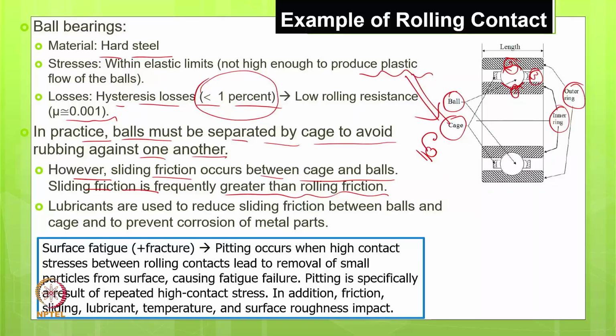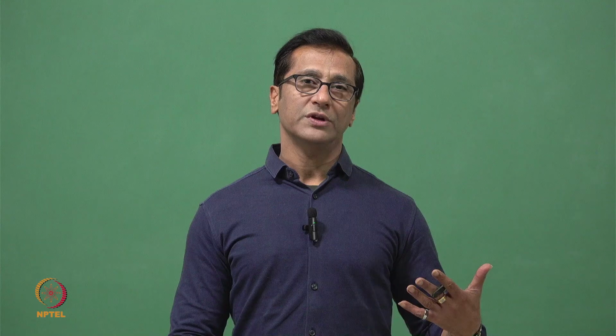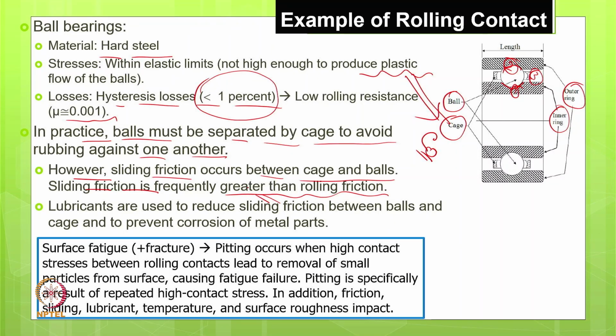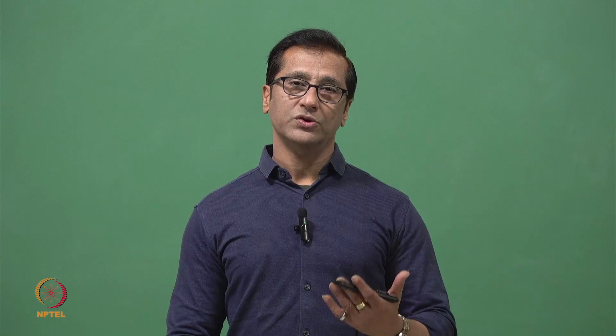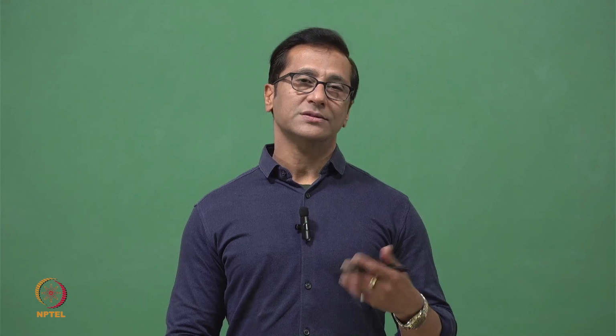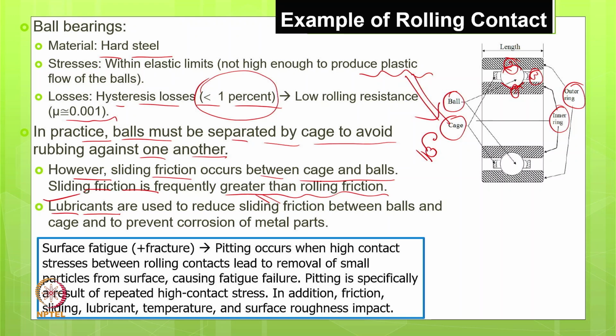And the needle roller bearing is known for that. We keep it fully complemented, and the highest coefficient of friction, I think 0.0045, belongs to the needle roller bearing. Now, to reduce this kind of sliding friction, often we use a lubricant, and I say NLGI grade 2, or maybe NLGI 1 or NLGI 3, depending on the requirement. We use a grease lubricant, more often grease lubricant for the rolling element bearing. But if a centralized system is really required, then we can go for liquid lubrication also. Now, this lubricant is trying to reduce the friction.